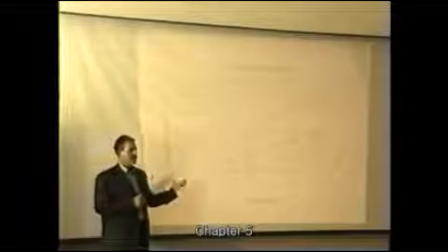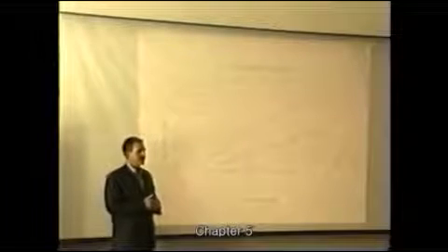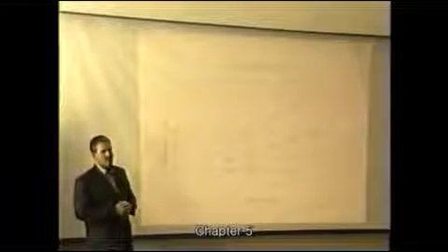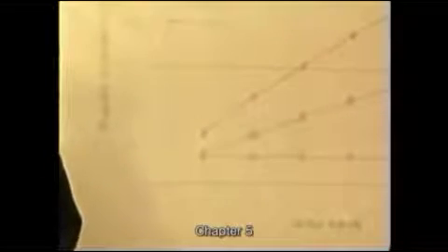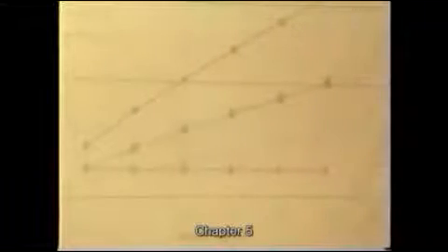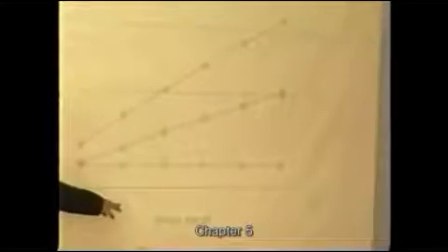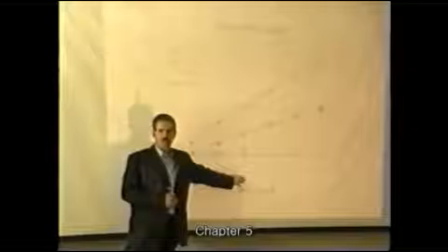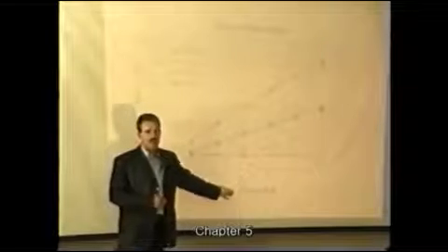So if you want any nitrification to happen, you would require extremely high mixed liquor concentrations. As you can see, to get underneath this straight line, you need to run at about 6,500 mixed liquor total solids concentration. But that will give you only a 10-day sludge age. And if you want any nitrification to happen, you would require almost a 15-day sludge age.